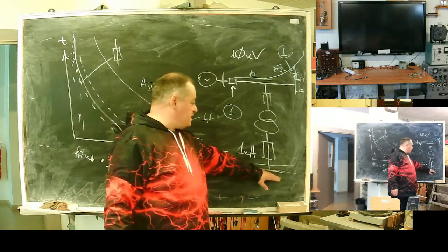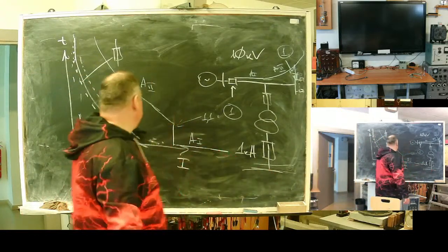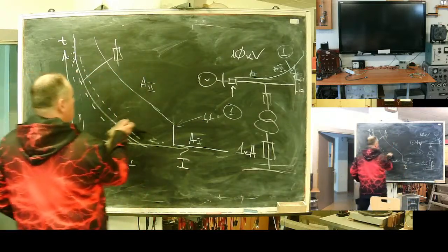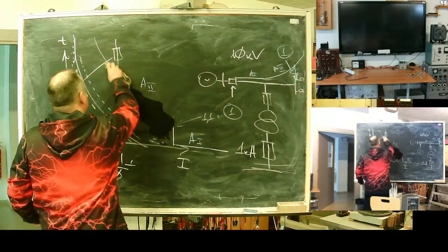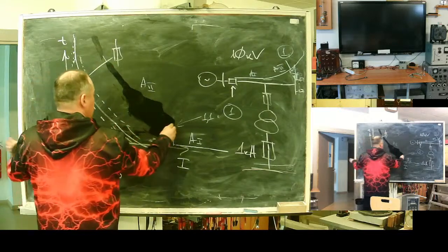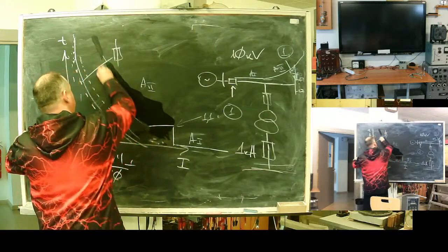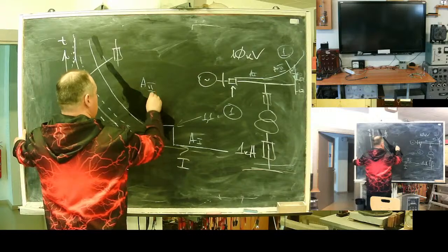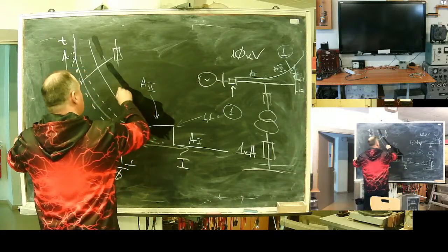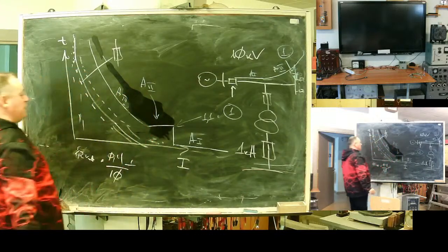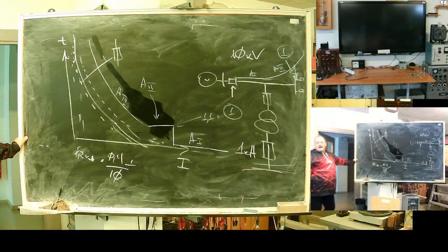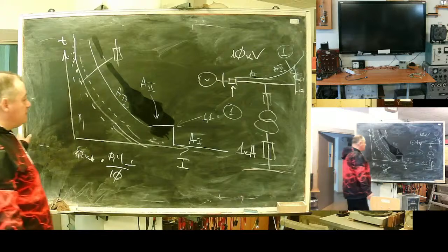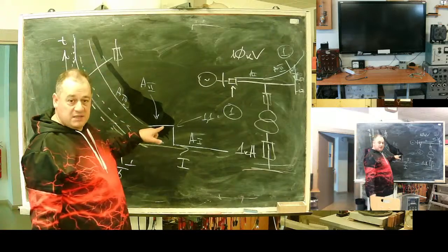It will be sensitive to a fault on this bus, more sensitive. With a digital relay, very typical for digital relays, they offer us up to 5 zones. And the last one, time dependent.